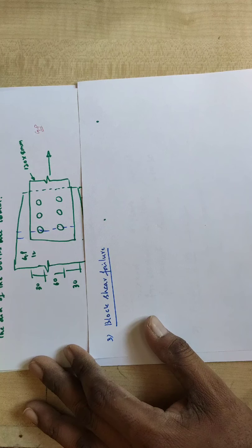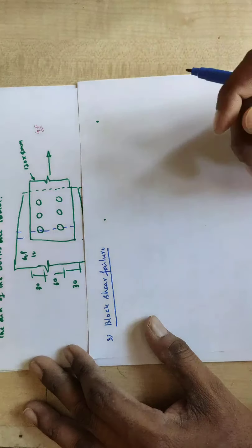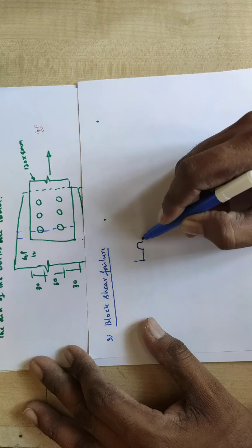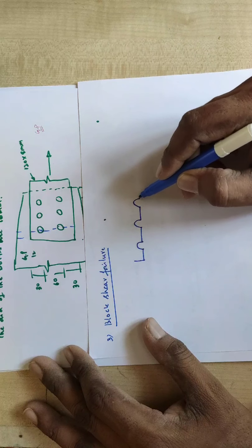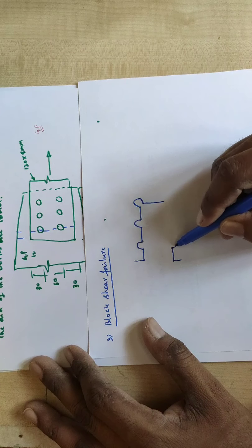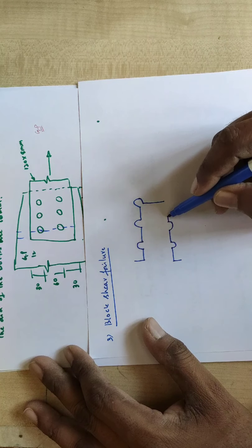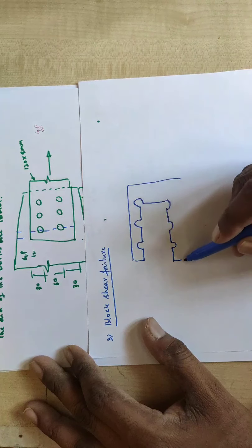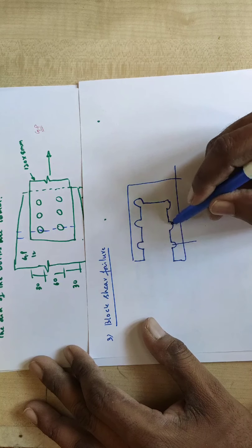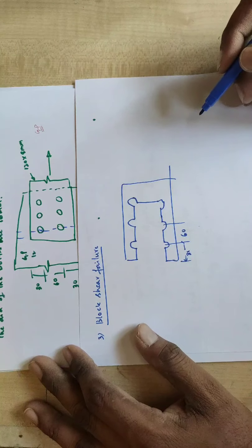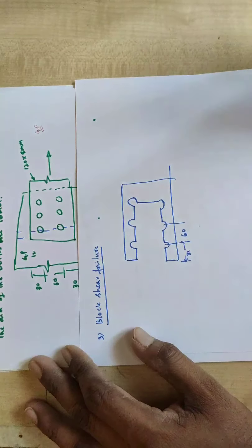Now, the third step is to calculate block shear failure. This is the important part here, and you have to understand this first. By referring to the diagram, if you draw a small diagram here, these are bolts. How many bolts are there? Totally 3 bolts, and again the same here, we have 3 bolts. What is the dimension? If you arrange them here, you can see the pitch, center to center, is 60 and the edge distance is given as 30 mm.